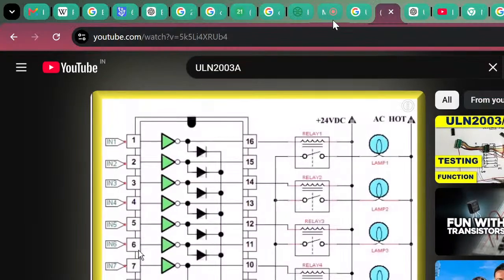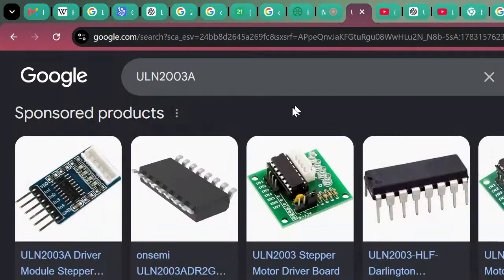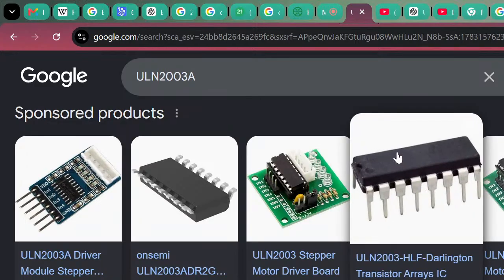This is how that component looks. If you want to connect a relay with something like a battery, you can directly connect it. But if you want to connect it to something like an Arduino Uno or ESP32, ESP8266, or any microcontroller architecture, then you need to use this particular component, because it is the safest practice. It is the safest method.